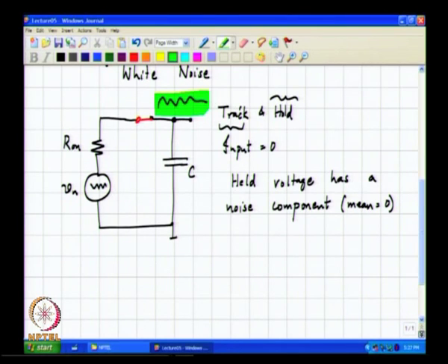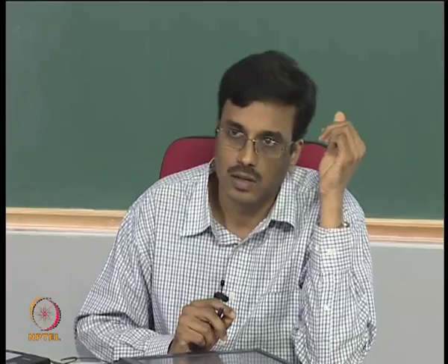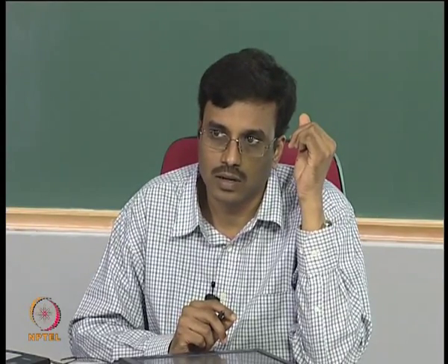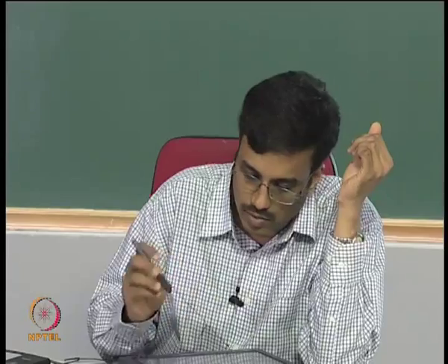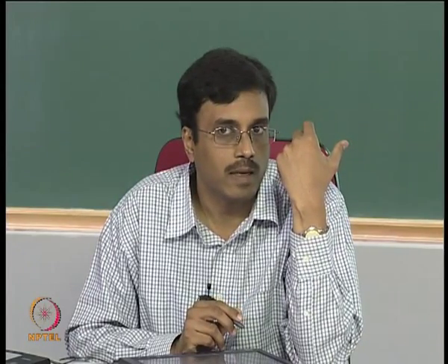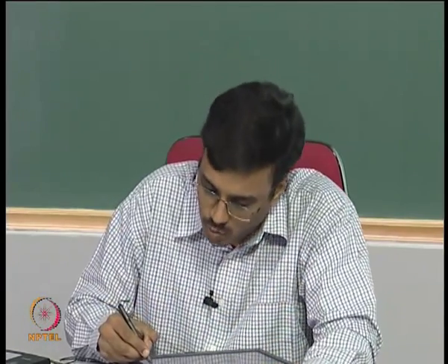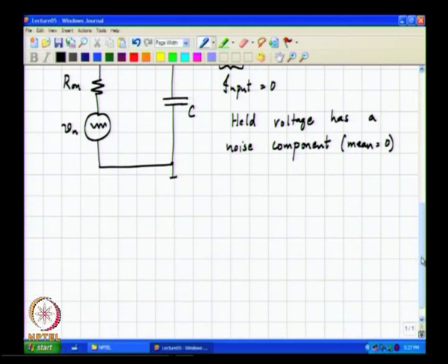Transfer function whole square. 2 kT. Pardon? After closing is steady state. 4 kTR into transfer function whole square. Transfer function whole square, and what is the intuition behind that? So, what is happening? The answer is indeed right. So, we have a noise source with some spectral density SV of f, which happens to be 4 kTR volt square per hertz. Okay.